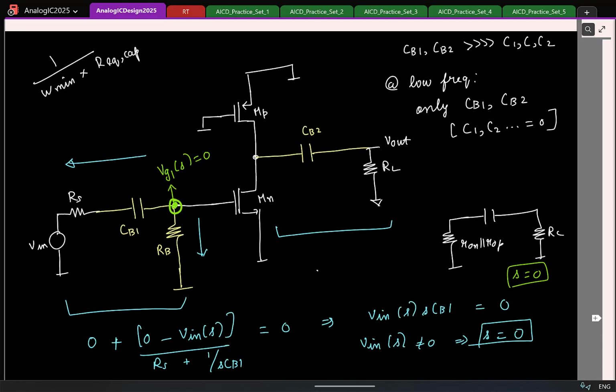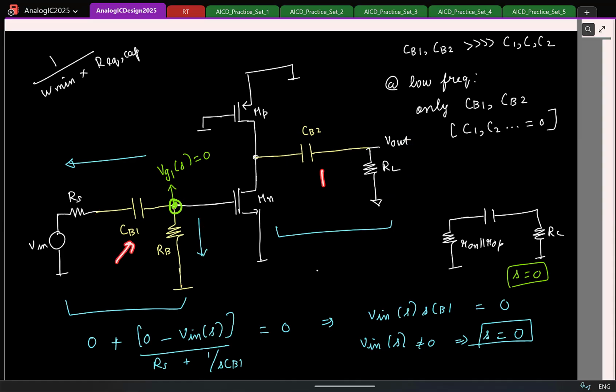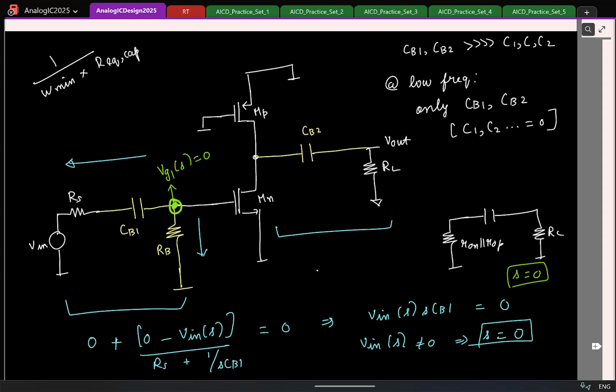So the point to have in mind is, anytime you have this AC coupling business, each of those capacitors will give rise to a 0 at S equal to 0, and then you have poles to counter that, because if those poles were not there, the gain would keep growing, but of course that doesn't happen. So you have a pole and a 0 associated with it.